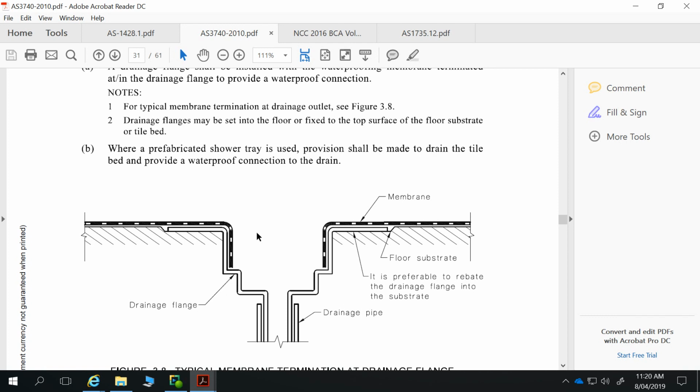So let's say we were building a house with an elevated timber floor, and we didn't want to produce a set down in that elevated floor. We really wanted to cheap out, and we wanted to keep that framing really simple. Another way we can do that, so we don't have a set down for our wet area sloping to a floor trap, is to have overflow protection on all of our things like laundry tub, hand basin, and bath.